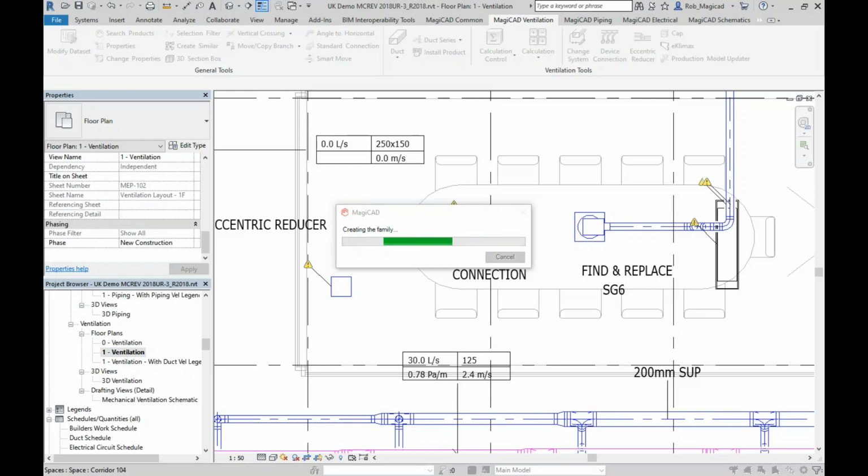So when it's done that, let's give it a few seconds to manipulate that family, and when it installs it, I'll show you where you can access the parameters. And it's worth mentioning at the moment as well why it's doing that. I'm showing, just happen to be showing, because I'm in the UK, these COBie parameters, which are quite important in this market area. People demand them on projects. It's a set of standard parameters for those who don't know that projects and products can be delivered in.